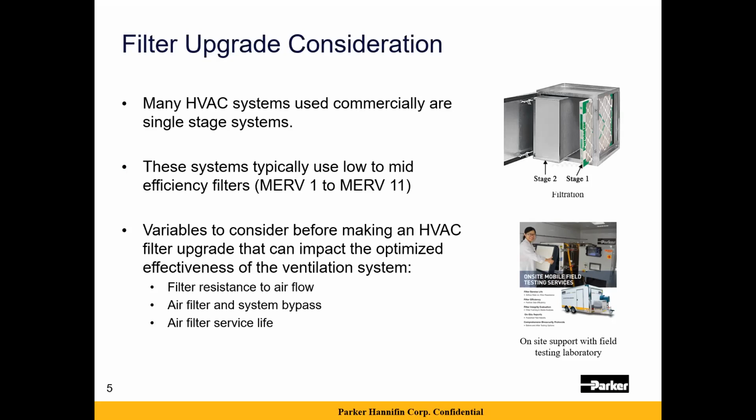So, that can be done, but there's a lot of variables that have to be considered before you want to make that type of filter upgrade, because changing the filter efficiency can have impacts on the effectiveness of the system. And those impacts can be the filter resistance to airflow, system bypass, and system service life for the filters.